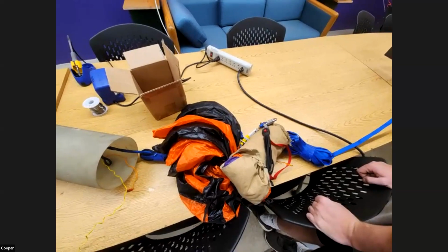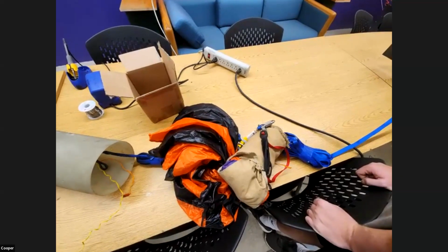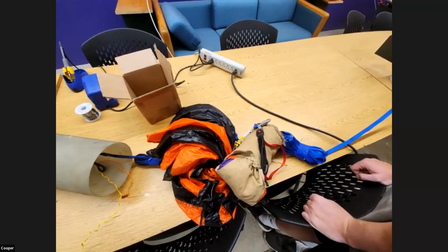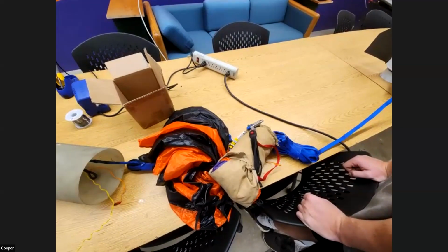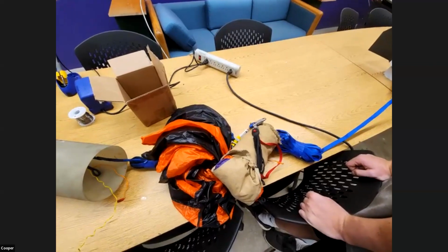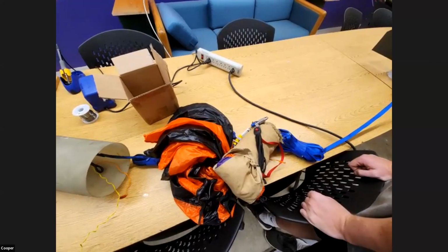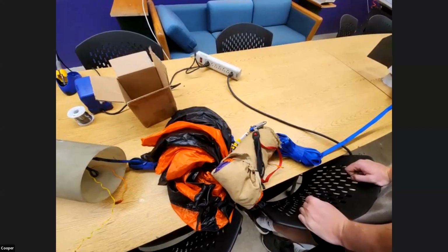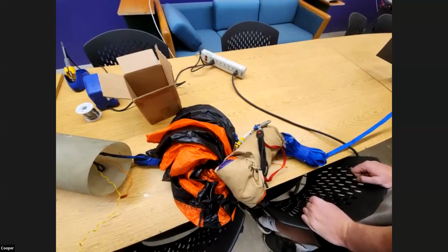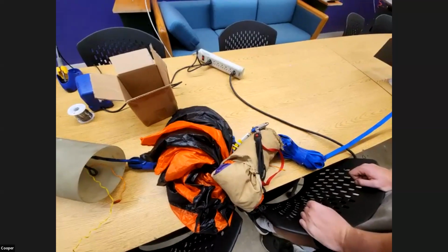I would not put them into the bag like you have it now. In fact, during normal operations, I would never even store a parachute in a bag like that, because if it sits in there for more than 12 to 14 hours, it'll start creasing, and you get a potential risk that it won't fully open up.